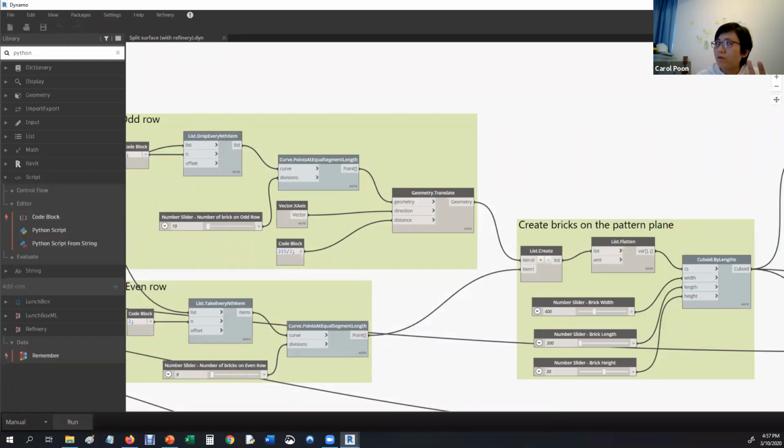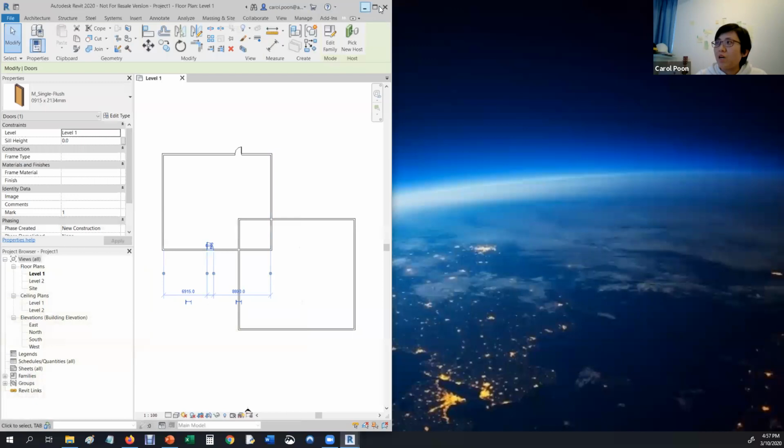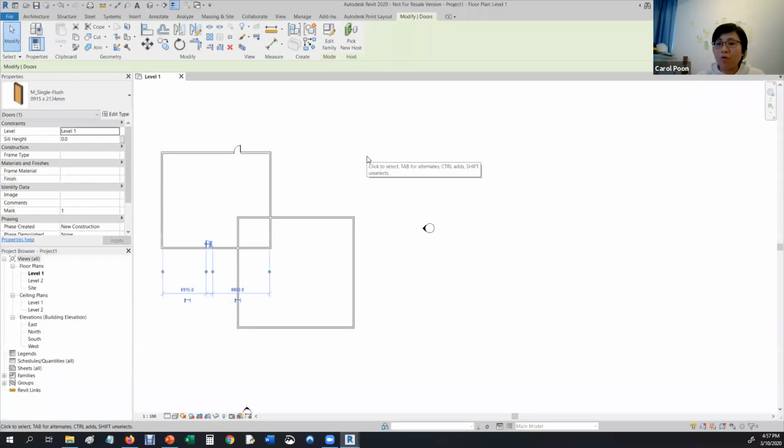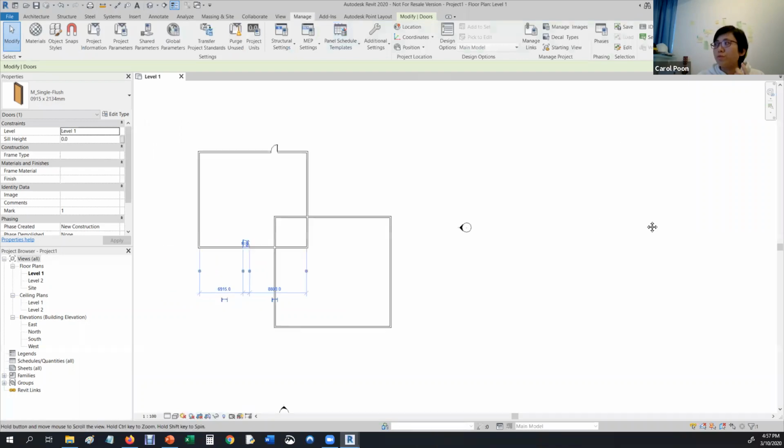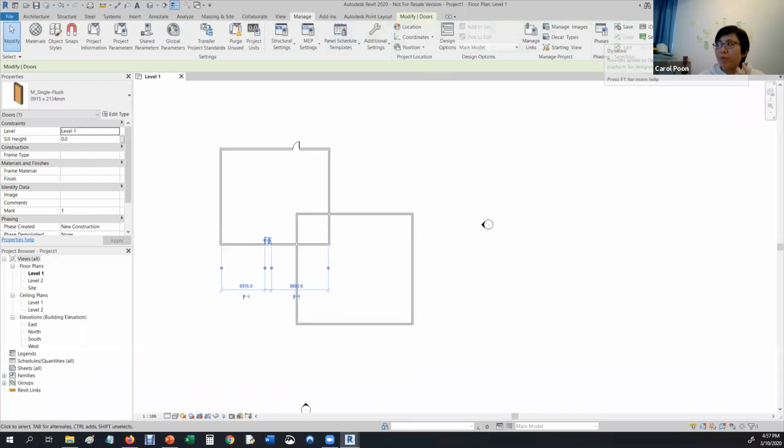And once you have downloaded the other version of Dynamo, you may ask whether Revit or our computer will override our Dynamo version. Actually, no, because every time you launch Dynamo, Revit will ask you which version you would like to use. Then you can choose the version you would like to use for your project.